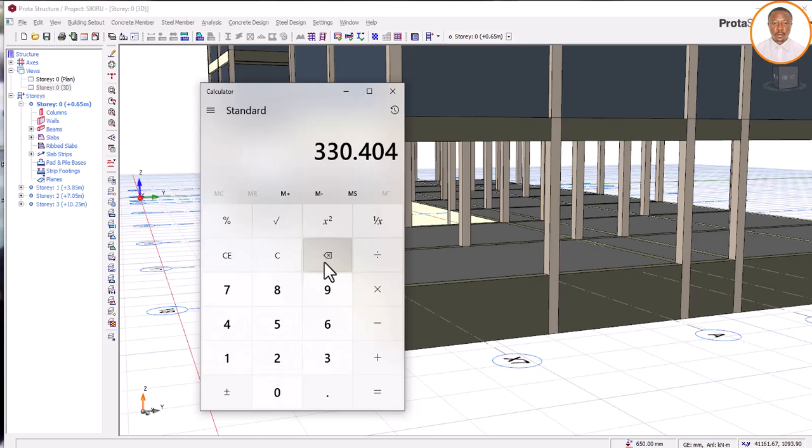Because once you put this value there and it's not enough, we have to come back and increase it. Since this is our minimum, just like when you are designing your column, you have an assumed section of your column. When you are designing your beam, you have an assumed depth of beam. Is that okay? So if you use this, there's a tendency that it might not pass, because this is the minimum you can start with. You cannot start less than this. Is that okay? But for me, from experience, I would say that you have that value.